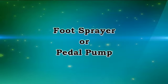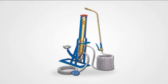Foot sprayer or pedal pump. A pedal pump consists of a vertical pressure chamber mounted onto a stand and a plunger assembly with the plunger rod attached to a pedal, in addition to a suction hose with a strainer, a delivery hose with an extension rod and spray nozzle.